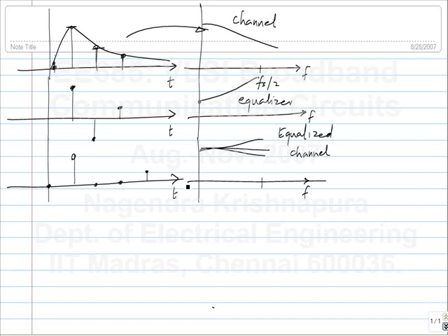We also came up with an algorithm for choosing the taps. We firstly said that the number of taps in the equalizer must be more than the number of significant ISI taps in the channel response. Okay. I say number of significant taps because you can have a truly infinitely lasting response, so you won't have infinite number of taps, but we will look at where the response becomes negligible and truncate the response to that many taps.